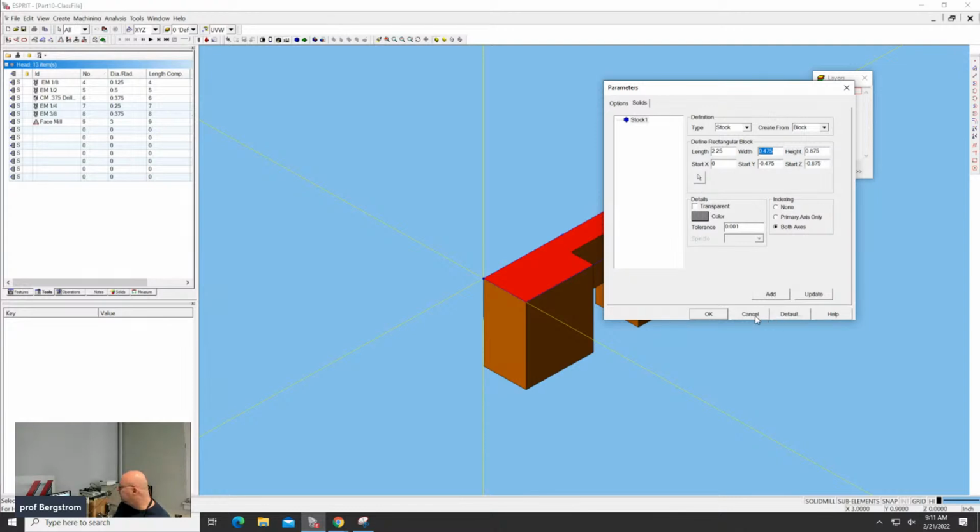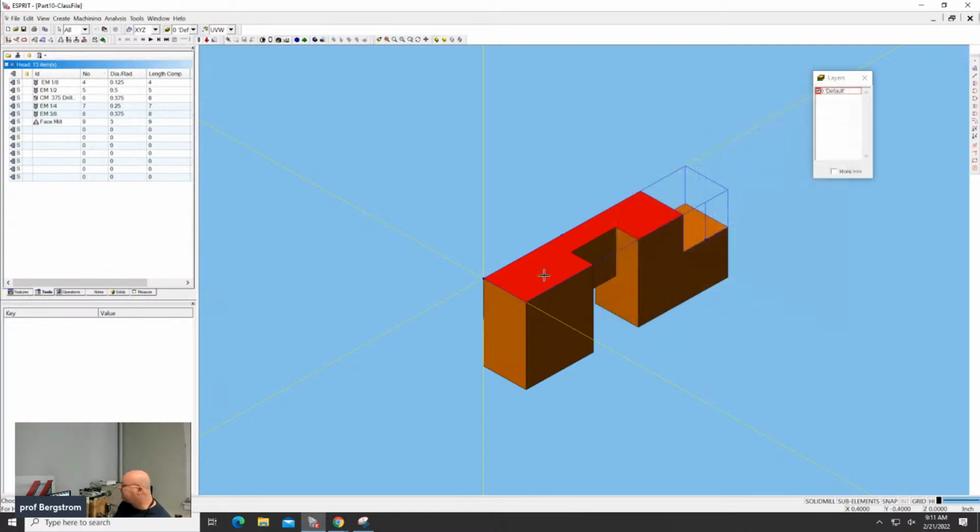So the top of the stock is right here at the same plane where that red plane is, which means we could do a facing operation there that would maybe touch the surface, maybe not. It depends on how well we set the work offset, how well we set the tool offset, and how level the part was in the fixture. Does that make sense?